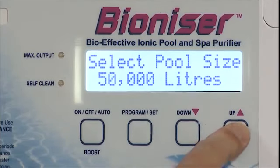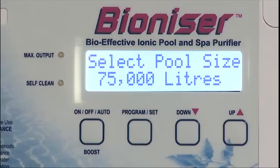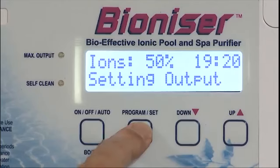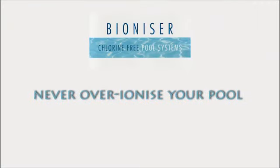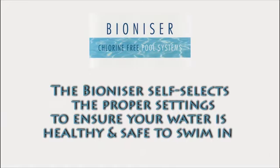Now, we know the pool size we have, so observe the process we use to set that figure into the Bionizer control unit. When the correct volume is on the screen, press the Program Set button to enter the pool volume. The Bionizer now automatically chooses the correct power setting and the correct amount of time the ionizer will operate for each day. This unique feature ensures that you will never over-ionize your pool and takes the guesswork away when setting up your Bionizer. In other words, the Bionizer has self-selected the proper settings that ensure your water is healthy and safe to swim in.